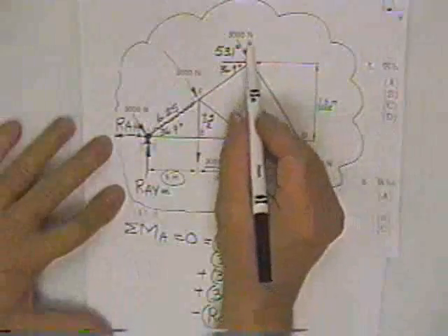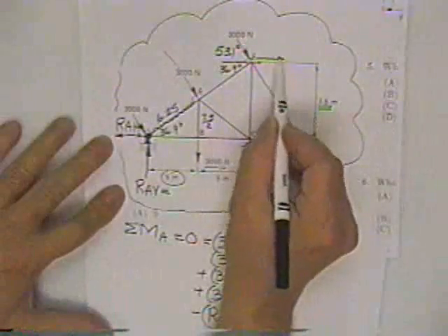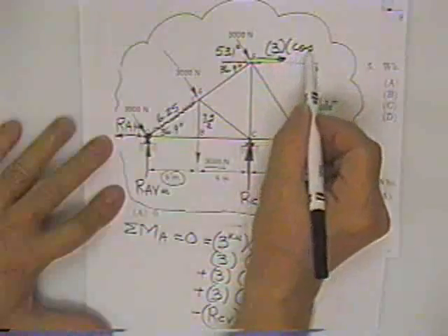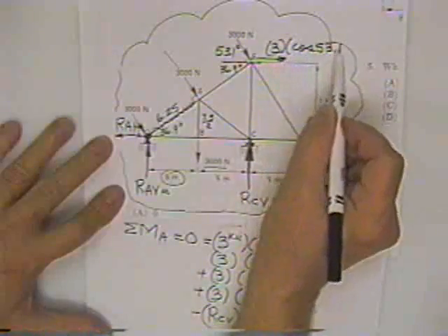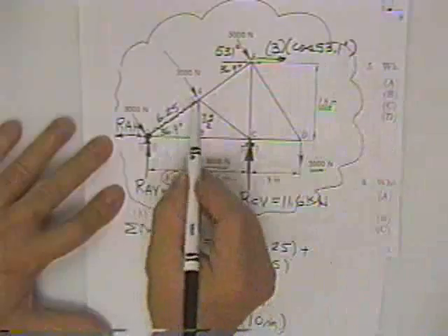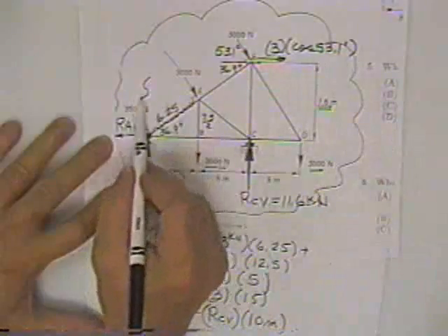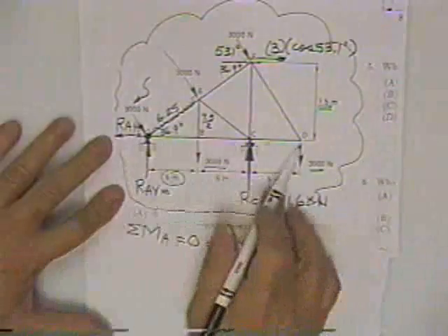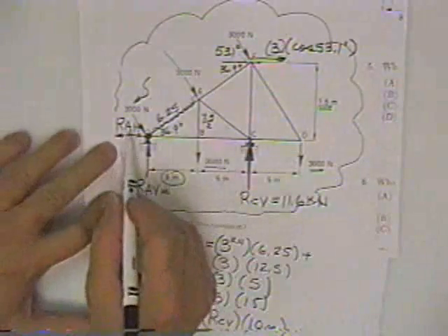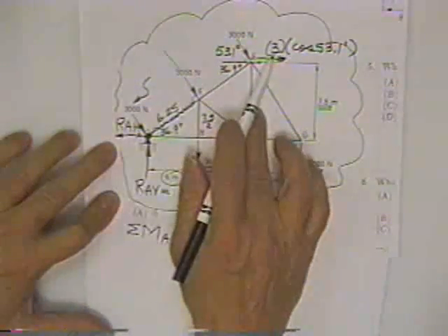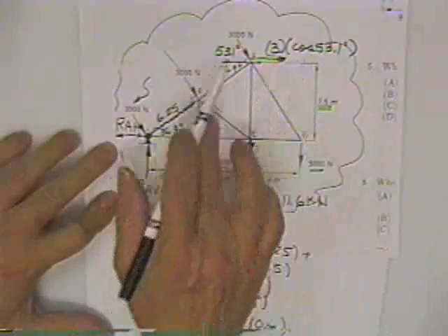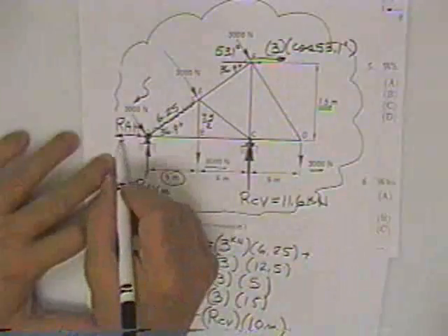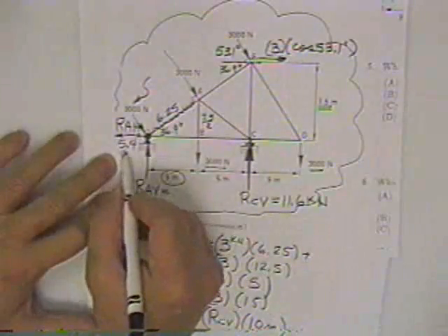So here again, we will find the horizontal component of this one by 3 kilonewtons times the cosine of 53.1. There'll be another one here. Don't forget this one here. This one counts. There'll be 3 of those. Those are the only people pushing to the right. This guy will equal to 3 times cosine of 53.1 times 3 of them. What'd you get for that? 5.4. 5.4 kilonewtons.